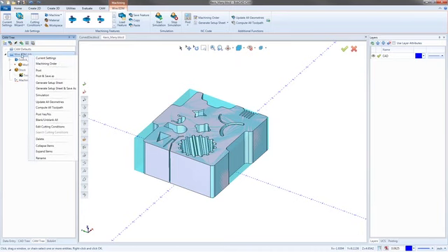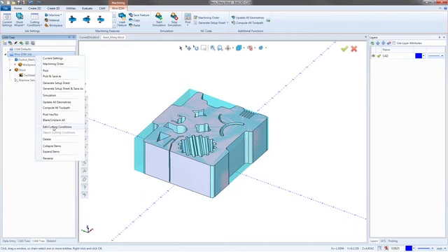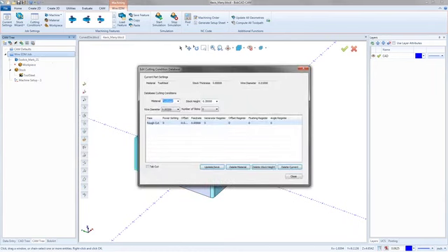So you can actually go in. If I right click on the Wire EDM job, I can go down and say edit cutting conditions. Now, when I get into the cutting conditions, I have a material, a stock thickness, and a wire diameter. I can set up a new material by adding materials, updating and saving. You can change the stock height. You can change the wire diameter. You can also change your number of skims. And then in that process, whenever you pick a piece of stock that's 3 inches thick with this wire diameter, it's going to pull up all your sizes properly.